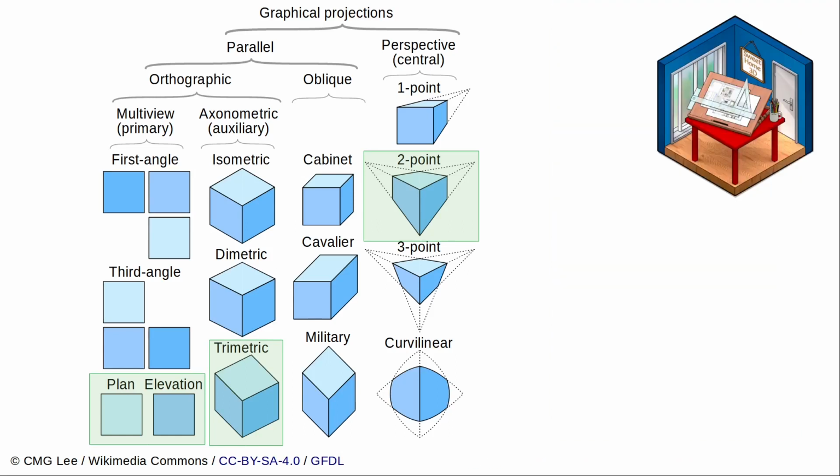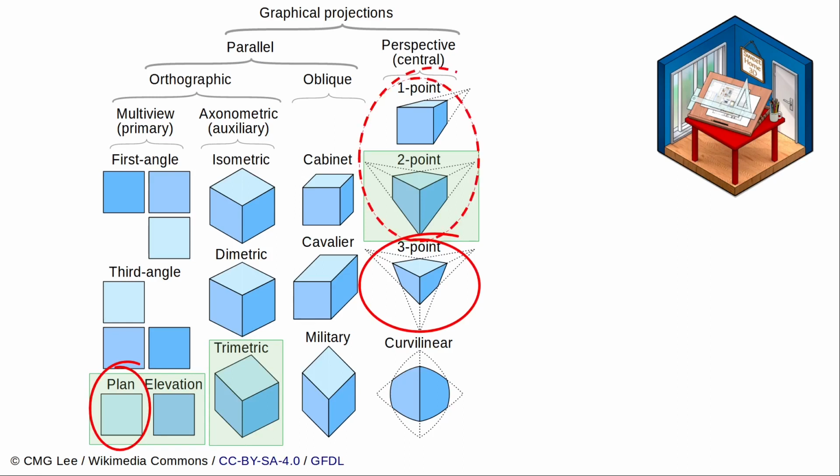Natively, Sweet Home 3D supports plan and 3 point perspective. Technically 1 point and 2 point are subsets of 3 point perspective, so you can create these images with Sweet Home 3D, but there is an issue. In order to get the 2 point or 1 point, you have to alter your viewpoint to be square to the axis.